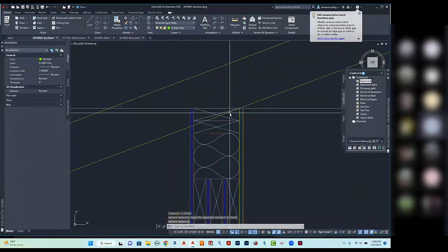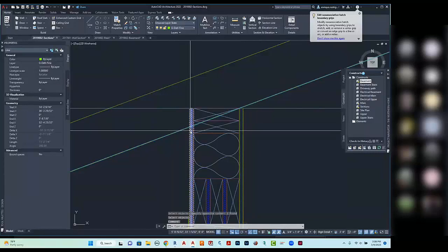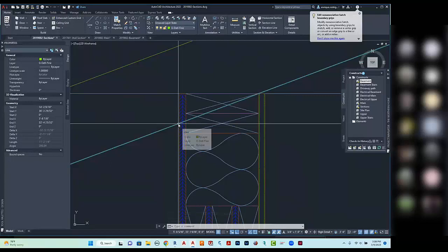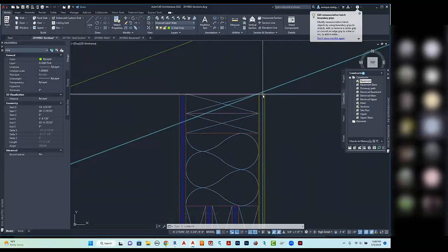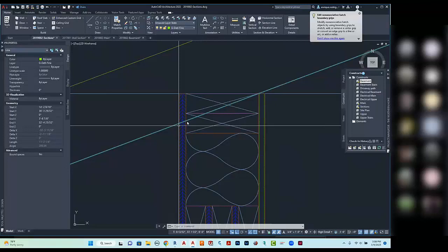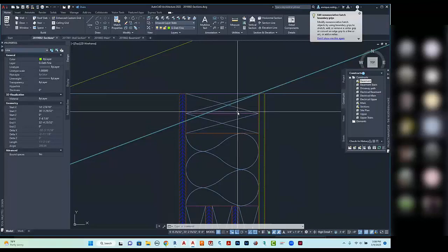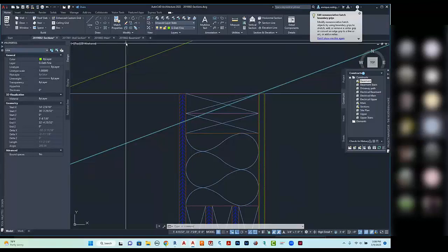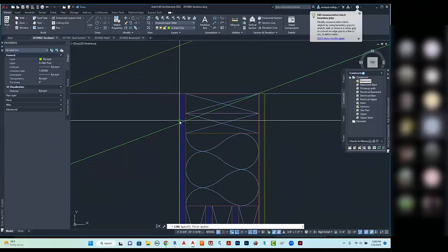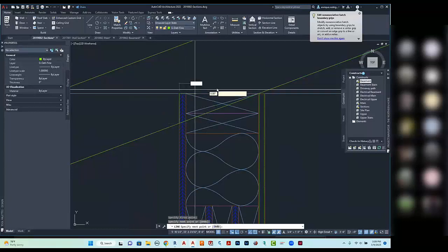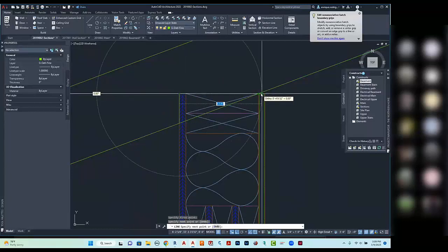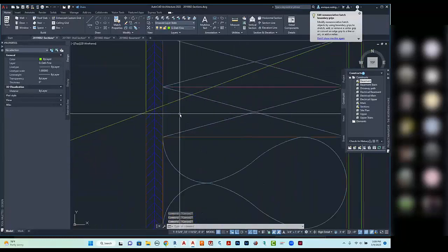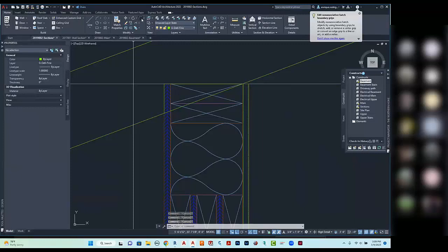Now, notice we can't have this rafter cutting right through here. So what we're going to do is we're going to go ahead and delete the rafter portion from here to here. So there's a triangular piece cut out right here. That's called the bird's mouth cut. You guys already knew that from the Marion when we drew that. So I'm going to go ahead and draw a line from here to here and to here. And I am going to go ahead and trim.